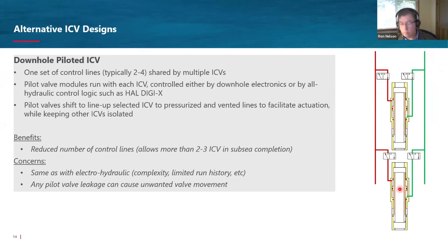I know this logic has been used in a few fields around the world. I think in parts of Asia, and also one field I can think of in Africa. The big benefit of this is the obvious one, that you're reducing the number of control lines. If you want to run more than 2 or 3 ICVs in a subsea completion, this is another way of doing it.